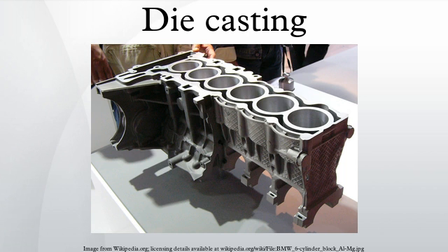The main failure mode for die casting dies is wear or erosion. Other failure modes are heat checking and thermal fatigue. Heat checking is when surface cracks occur on the die due to a large temperature change on every cycle. Thermal fatigue is when surface cracks occur on the die due to a large number of cycles.